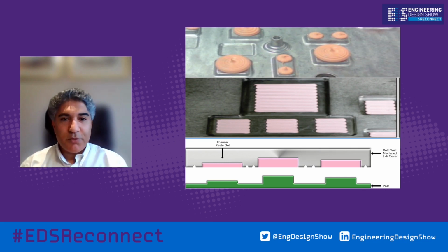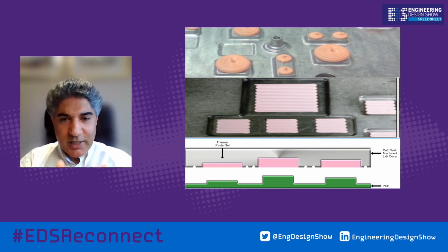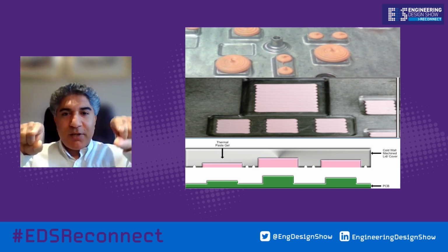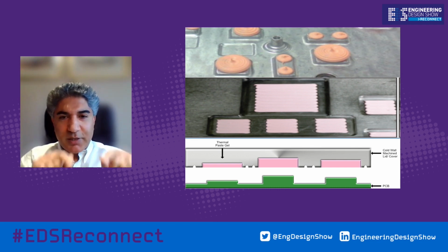Okay, as you see in the 3 diagrams here, the first shows the metalwork, the interface using the thermal paste, instead of dedicated heat sinks, you're using an interface or lid as a heat sink. The middle one is trying to show you interchangeability. There used to be a gap pad, but now it's dispensed in. You can have one whole piece rather than 2 or 4 separate pieces, to minimize touch time. The XYZ robot will dispense it to the shape that you want and the location.